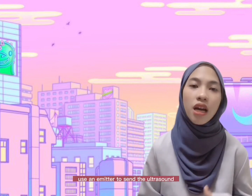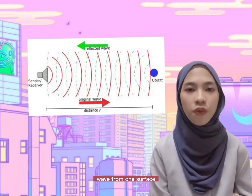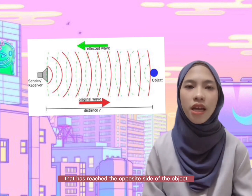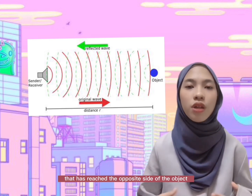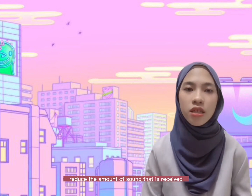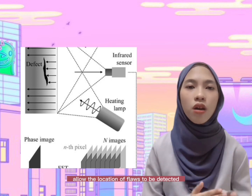Through transmission testing uses an emitter to send the ultrasound wave from one surface and a separate receiver to receive the sound energy that has reached the opposite side of the object. Imperfections in the material reduce the amount of sound that is received, allowing the location of flaws to be detected.